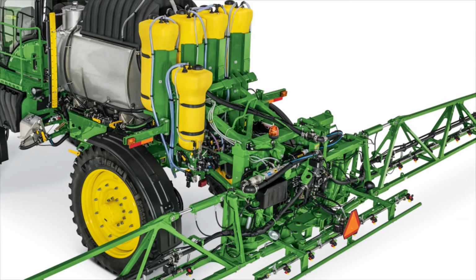So our high flow pumps run about 5 to 200 ounces per minute. The low flow pumps run between 1 and 40 ounces a minute. Now again, that's ounces per minute, not ounces per acre. Essentially what that equates to, if you think about product, a high flow setup would be something more like Roundup or a Dicamba or a Liberty type of product, where you're applying 12 to 32 or 40 ounces an acre, no matter your boom width. The low flow pump would be things more like DRAs or drift reducing agents. You're going to be closer to that 2 or 3 ounces an acre.